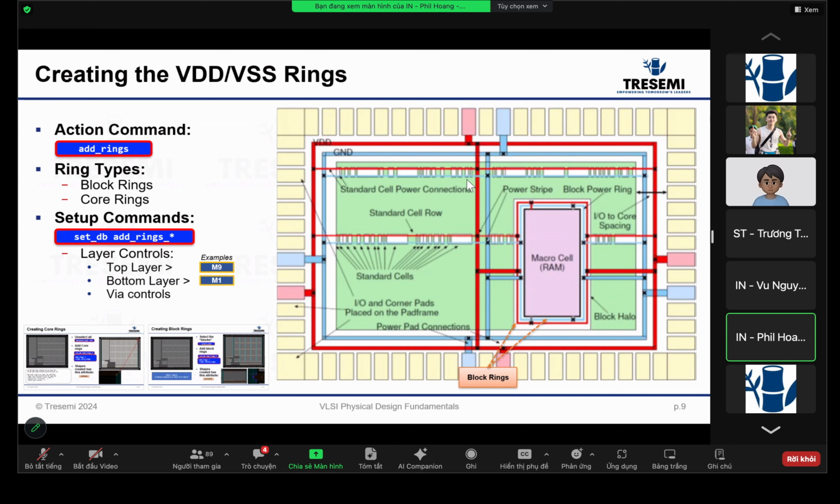The question is, in which case is the VDD of the IO pad lower than the VDD core. Today, for 22 nanometer or lower, the typical operating voltage is between 0.5 to maybe 0.9 volt. And for the IO pad, in the past it was like 1.8, 3.3, 2.5 volt. Now it's moving down to 1.0 volt. That's a typical LV-CMOS IO pad.